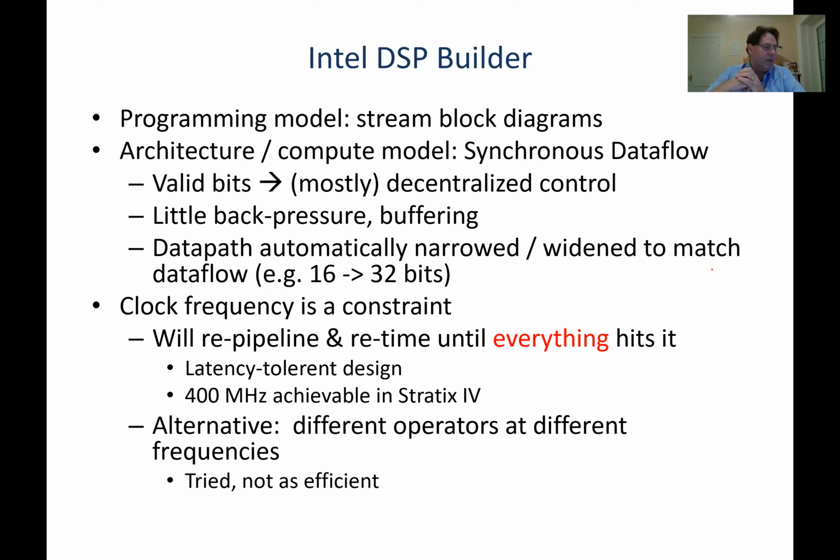It'll have many modules where it can guarantee that the downstream module can always keep up with the upstream modules, and in that case, it doesn't even generate back pressure signals. So it basically uses the simplest streaming model that it can for each part of the design.